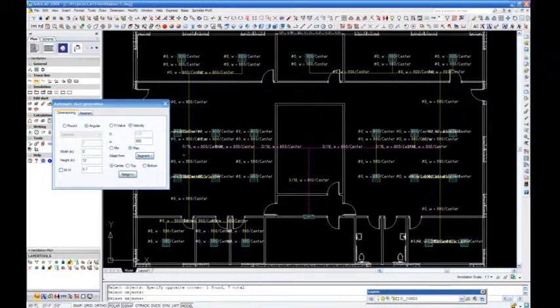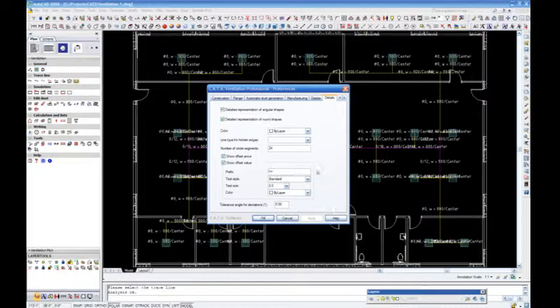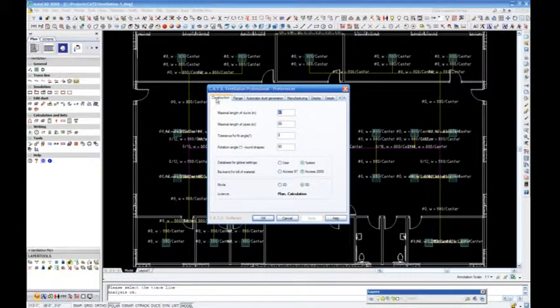In width, we will select 0. The software will calculate the duct width according to the velocity. As the air quantity reduces, we now change our duct height to 12 inches. We are now assigning our duct system to a three-dimensional drawing by selecting a start point at the fire damper.